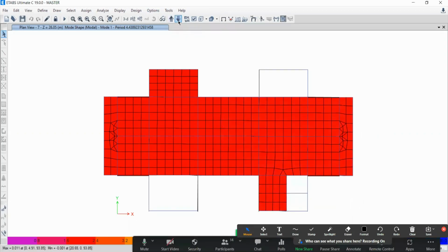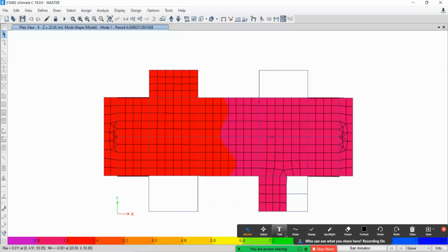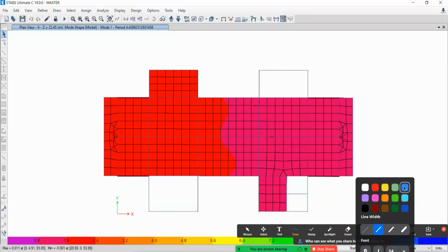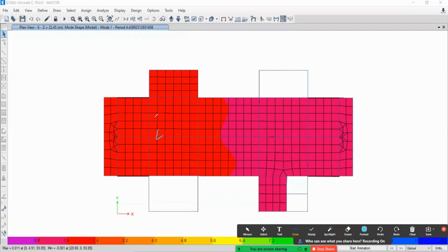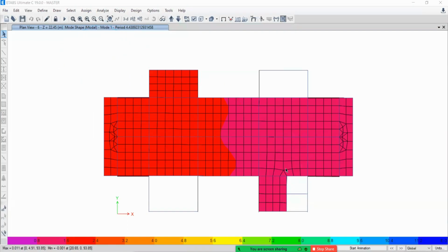Now here, but one thing, just come down. Another thing you can see here, another good thing: this color and this color are adjacent colors, this red one and this orange one. So the stiffnesses are very close. That's again a good thing. A greater difference is not there. If it were red and then directly green, then your structure would experience this kind of torsion. Yes. Okay. So that's how to read the results that I wanted to show you.